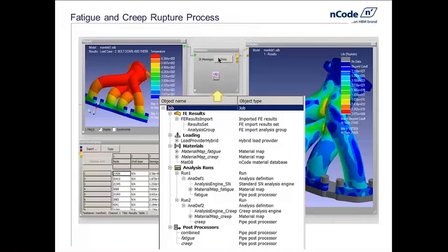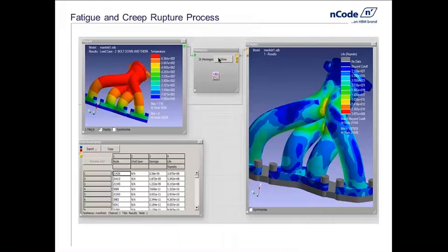The first analysis run is doing the temperature-based fatigue, looking at the time, temperature, stress profile and calculating fatigue damage from that. There's a second run that follows this, running the Larson-Miller creep rupture calculation, using exactly the same time profile, but calculating the amount of damage caused by creep rupture. And then DesignLife sums those two, using Robinson's rule, and presents it as results.